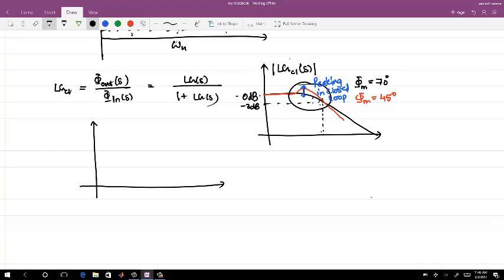When you give any step to the system, if the step is very small, not a large step, and all these loop gain analyses hold valid, then it will add to the jitter. But how exactly it comes as jitter, I think that depends. When we look at a ringing in the step response, the step at the input excites all the frequencies, so all these frequencies will then translate to the jitter.